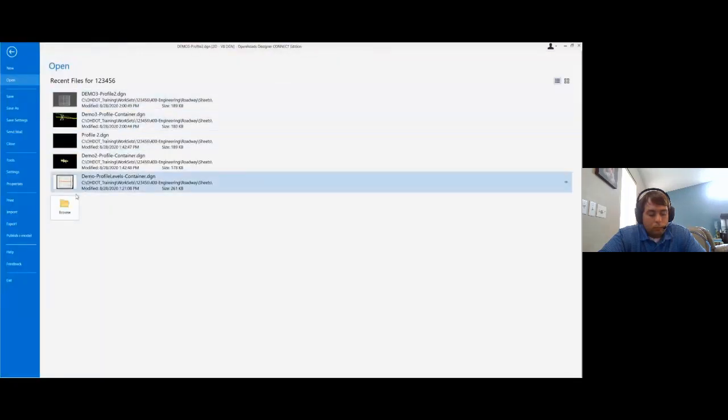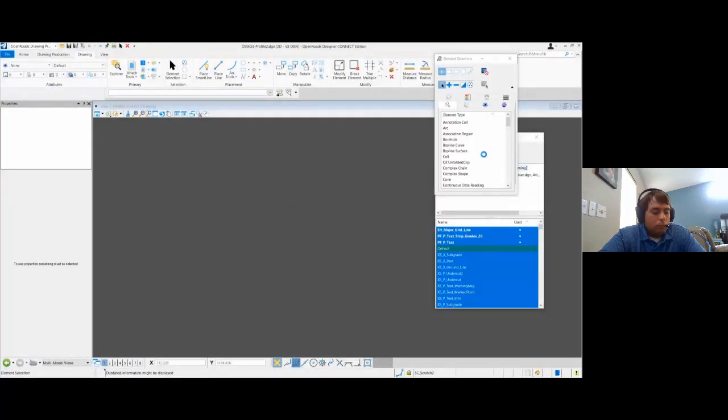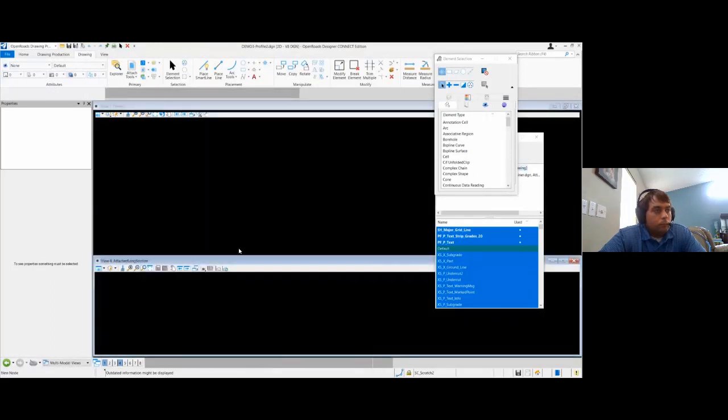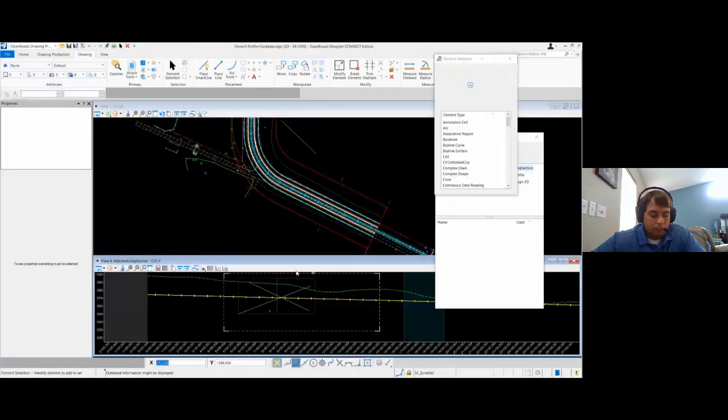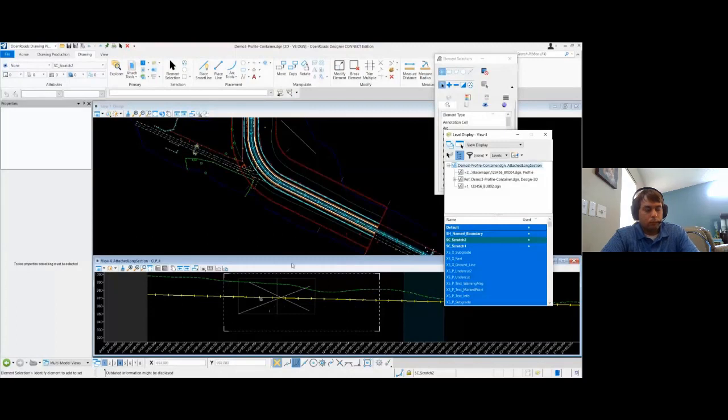So what you have to do is you have to use global display when you're within this profile view here. I think it has something to do with this not being like an exact real model, whereas your plan view was a real model. This is, like, within the geometry. So I think that is why view display isn't working with the override set to never.